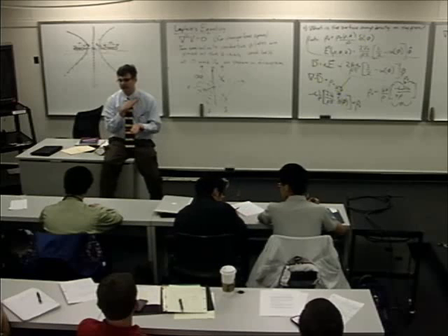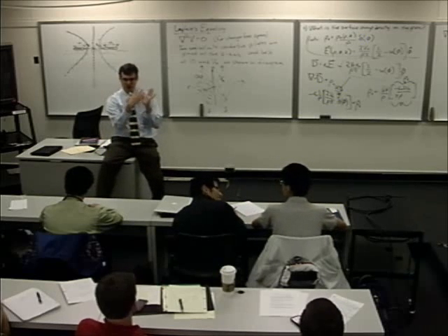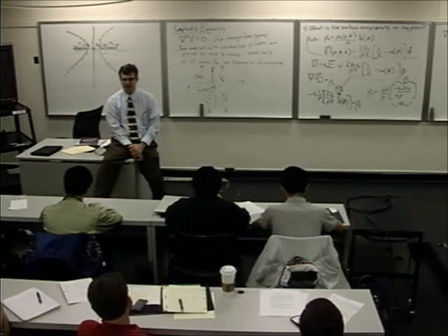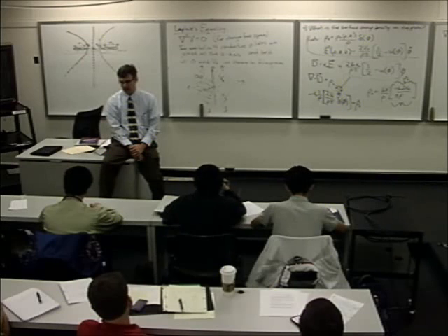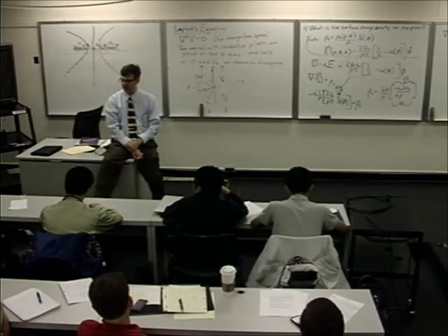This is what you also coat the front part of solar cells with. If you think about it, you need to metallize both sides of the solar cell, but one of those has to let in sunlight, right? If you put ITO on one side, that's really the first widespread use of it. But I also know it's a brittle conductor. So if there's a lot of mechanical pressure deforming the surface, depending on how it's manufactured, you can actually make invisible breaks in the material that open circuit the connections.